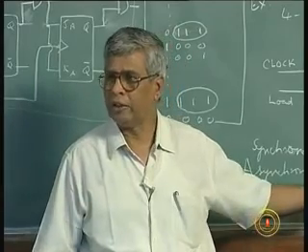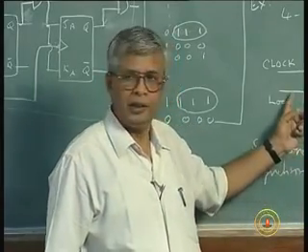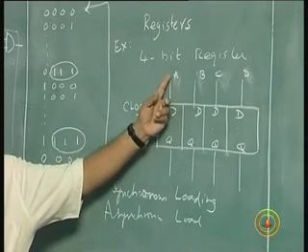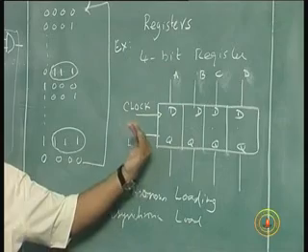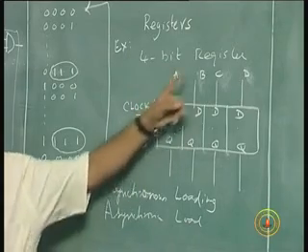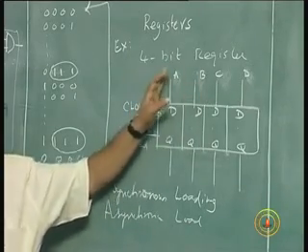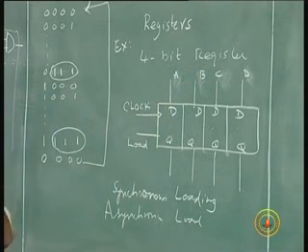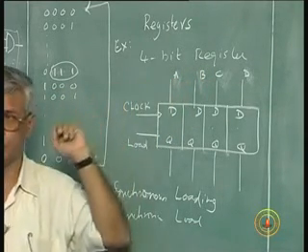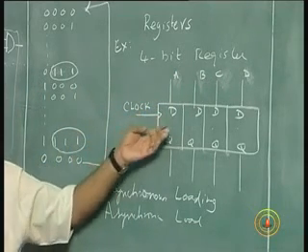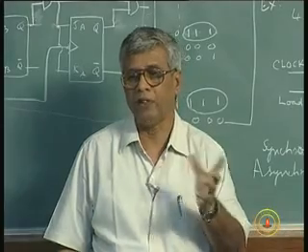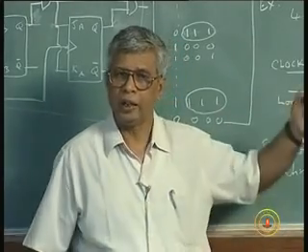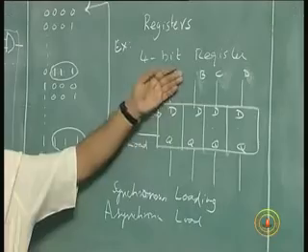Now with the load I have this control. I can apply the load at the time when this data was available and remove the load pulse, and then the clock may come and go, but the new junk value cannot enter. Even though the original values have been removed, the arbitrary random values that ABCD assume do not get into the flip-flops until another load pulse comes. So after reading the data after 100 microseconds, I can put one more load pulse and capture one more set of data.